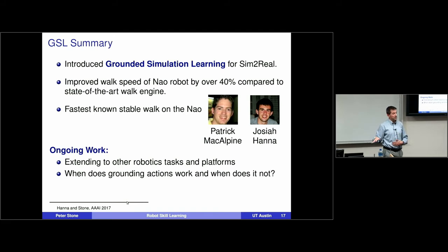The thing that makes it more challenging on the humanoid robots is that on the quadruped robots, if you have a bad policy, they're still stable. These robots, if you just take random perturbations, they're falling over all the time. They're breaking. It just wasn't viable to get enough training data, and it's a much more complicated dynamics problem. Rather than a 12-dimensional parameter space, we're at more of a 30 to 50 dimensional space, and so we got to the point where we couldn't just do this all in the real world in a scalable way. So that's... Find the solution analytically?